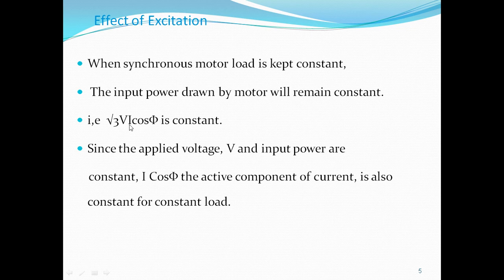Both are inversely proportional, so the product of current and power factor is constant. The product of I into cos phi must be constant. Then only the input power is constant.